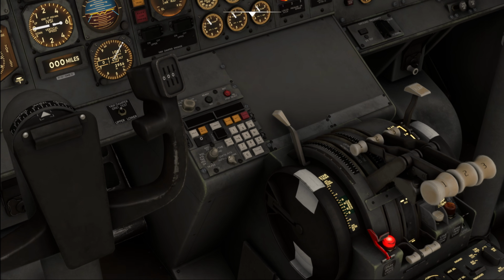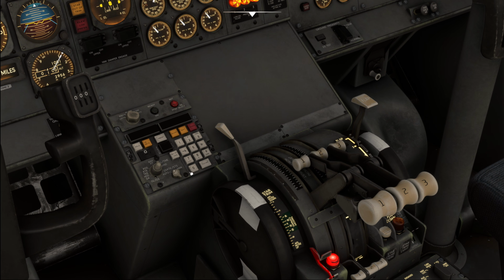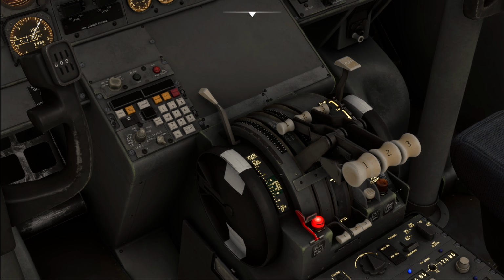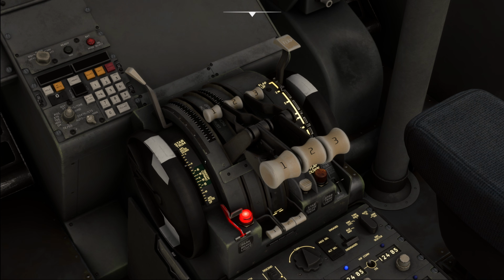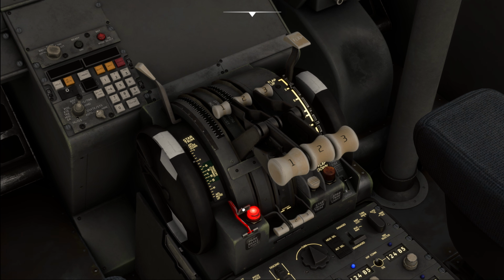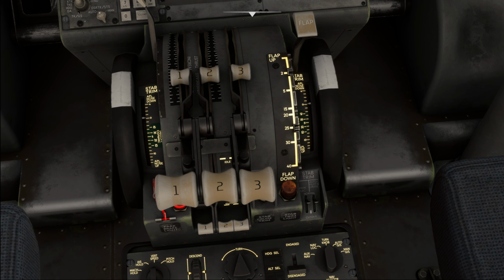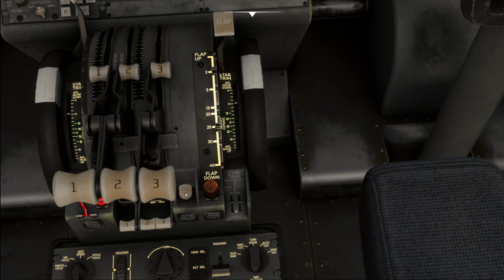Moving down then, we have our control stand. I'm intentionally skipping over the INS here. That will be dealt with in the navigation part of the tutorials. Moving down to the main panel, our stabilizer trim is set to 0 degrees up here. Parking brake is set. Fuel cutoff switches on cutoff. And moving over to the right hand side, the stabilizer trim switch, neutral, the step trim light, tested, works. And finally, the stabilizer trim switches are both in the up, so in the normal position.